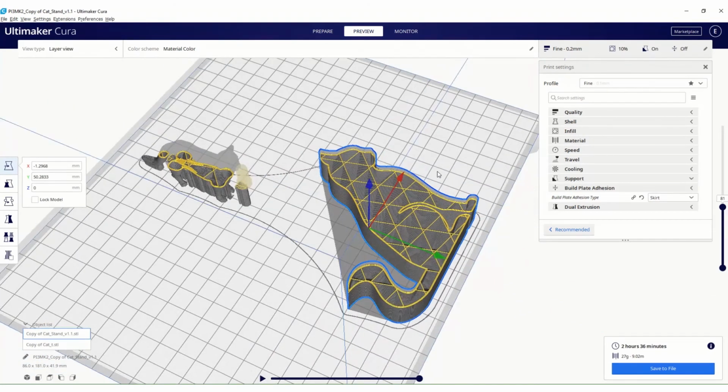What it's doing is clearing out the filament that's inside the nozzle from your previous print, and it's getting it all out of there. So to make sure that the filament that you're going to have for your model is really good. There's no little bit stuck in there, because sometimes your nozzle can get clogged up if you're using, let's say your previous print you used PETG, which has a higher melting point, and then the next one you're going to do is PLA, which has a lower melting point. So you might still have little chunks of PETG stuck inside your nozzle, and having a skirt helps to have everything run out, everything clear up.